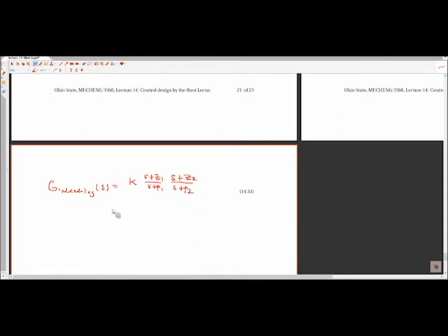And then we have the constraints. So we said this is the lag. This is the lead. And then we'd have the constraint that we have this sequence of zeros and poles for our system. So no real mystery. Design the lead. Make sure that's good. Design the lag. You just combine them together. That's your combined controller for your system.